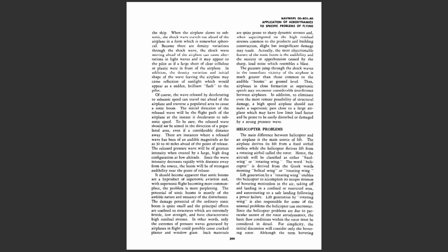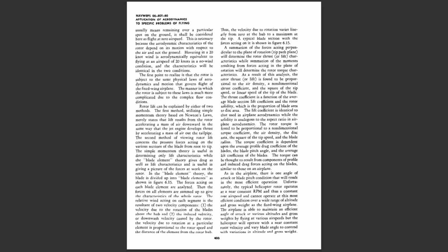Since the helicopter problems are due to the particular nature of the rotor aerodynamics, the basic flow conditions within the rotor must be considered in detail. For simplicity, the initial discussion will consider only the hovering rotor. Although the term hovering usually means remaining over a particular spot on the ground, it shall be considered here as flight at zero airspeed. This is necessary because the aerodynamic characteristics of the rotor depend on its motion with respect to the air and not the ground.